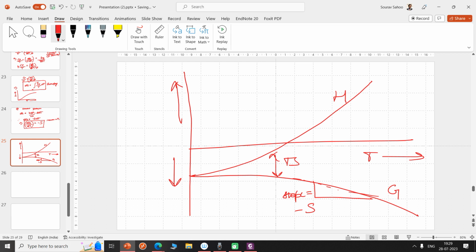For example, if you take a transition from solid to liquid, there will be a certain latent heat of fusion required at the melting temperature, Tm. There will be a certain change in the enthalpy, and correspondingly we will have a more negative free energy, corresponding to the free energy of liquid, which is stable at T greater than Tm.